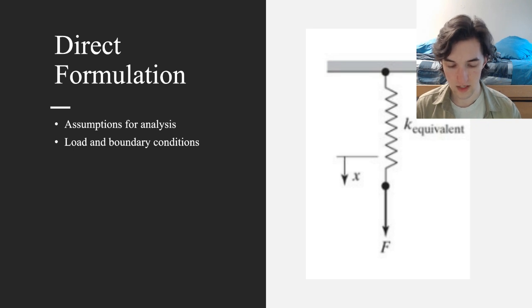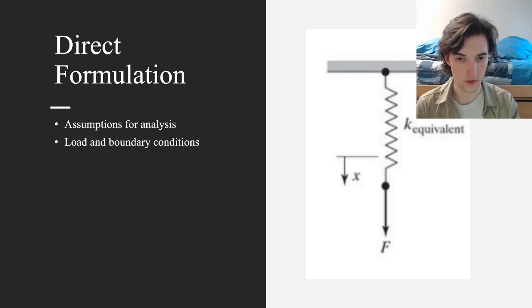For the direct formulation, we will be treating the stream as a resultant force, a compressive axial force on the deflector, and we will be ignoring any bending stress to make the calculation simpler. We will also be ignoring any of the teeth shown in the 3D model because that would add more to this analysis that we don't necessarily know yet. But if we were to add those teeth, it would be as simple as adding more springs and more nodes.